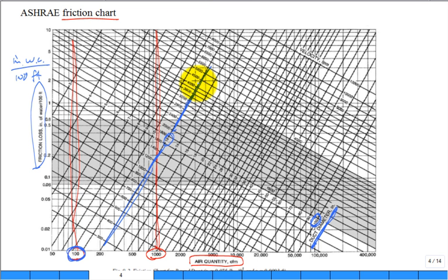So, if somebody said, I want you to push 100 CFM through a 12-inch duct diameter, round, galvanized with that standard roughness, what's going to be the frictional loss in it? It's going to be so low, you've got the wrong size diameter. It's going to be intersecting way down here off the chart, right? You could push 1,000 CFM through 12 inch. It would come up right here. That's where you intersect, and it's going to cost 0.2. That'll be the friction loss. 0.2 inches of water column per 100 foot.